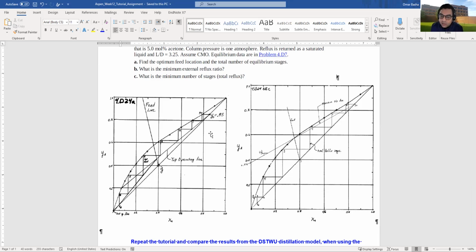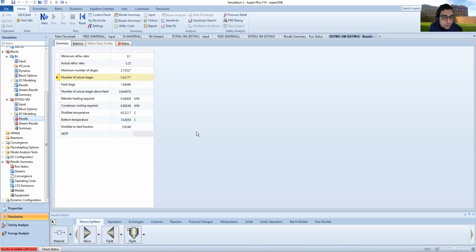They're not going to be identical because the Underwood equation will not give you the same number as the McCabe-Thiele method, and the tool you're using for McCabe-Thiele will change from person to person. Some people are very neat, so they can get these lines, perfect slopes and everything. Some people, just 1 degree in the line, and you're off by 2-3 stages, which is not a big deal at the very initial design when we're designing a process. However, as you close in on your distillation column, it starts to make a big difference in your metrics.